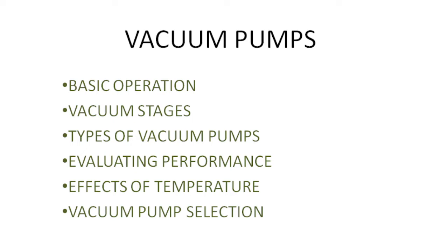Now, there are various types of vacuum pumps. There are oil-less and oil-lubricated vacuum pumps. As with compressors, the application normally dictates whether an oil-less or oil-lubricated vacuum pump should be used. Oil-less pumps are almost essential when production processes cannot tolerate any oil vapor carryover into the exhaust air, and they can also be justified on the basis of avoiding the cost and time of regularly refilling the oil reservoirs.